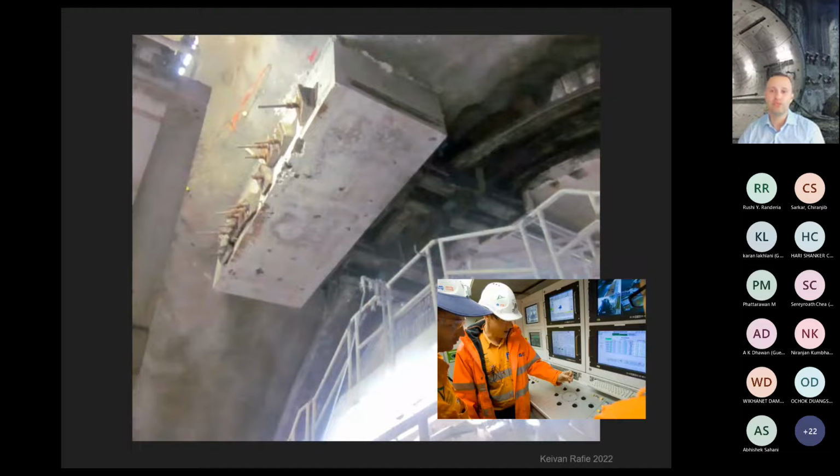Once the installation was complete, the cutter head was retracted by approximately 100 mm, and then the overcut was set to 0, just to make the best conditions for the release. The solenoids on the top rams were also reinstated, so we could have those rams at the top. And when we applied all that, we were successful in breaking the TBM free.